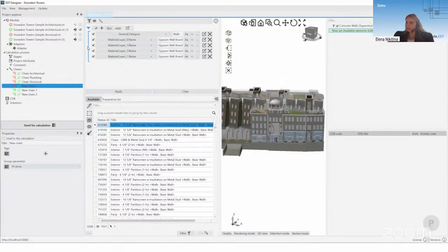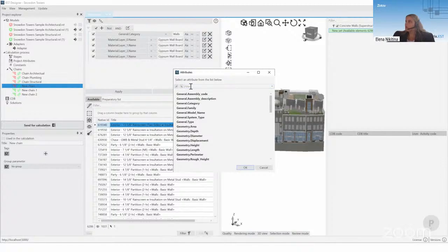The position number of this layer you can choose freely, but here we need to add 4 layers with gypsum wallboard because we want to calculate these types of partitions. Name 4.